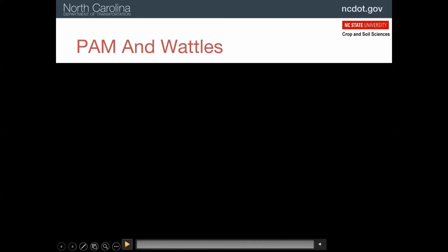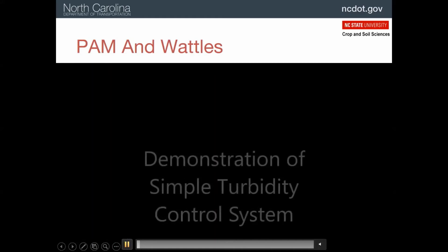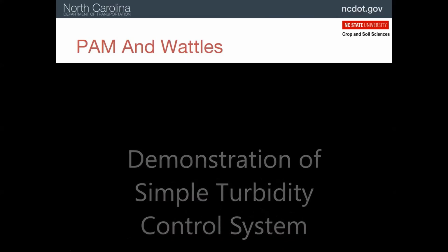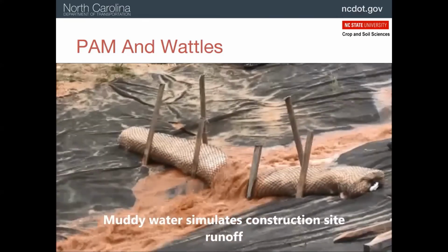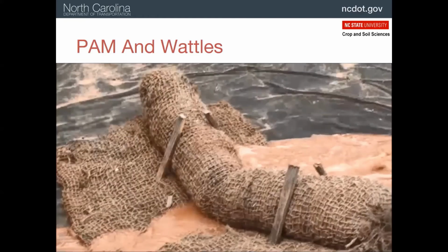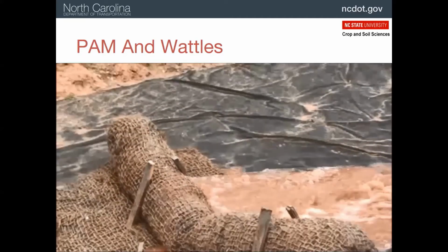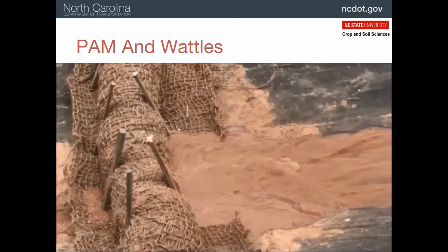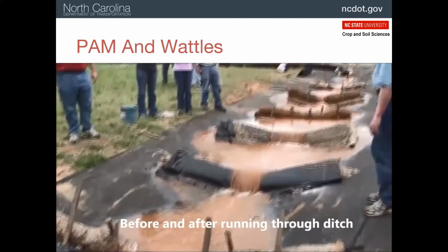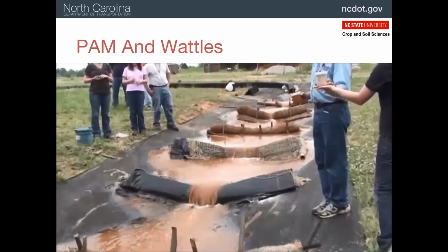All right, so here's a video. Again, if we were in the field today, you'd be seeing this live, but this will show you an example of how this works. So we have this ditch line that we can install practices in and send some muddy water in, and that's what you're seeing here. And we put polyacrylamide on each of these wattles. So now you're going to get a look at what it looks like at the beginning and the end of this treatment.